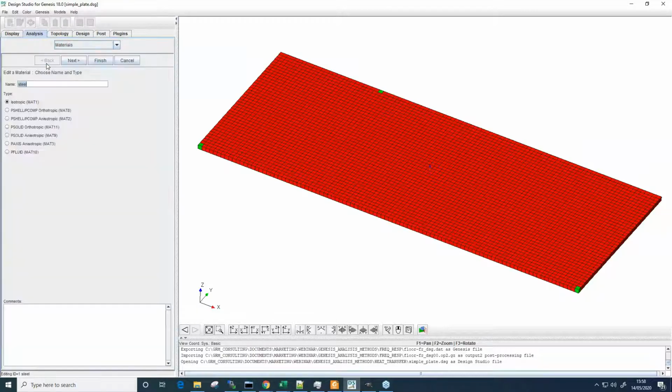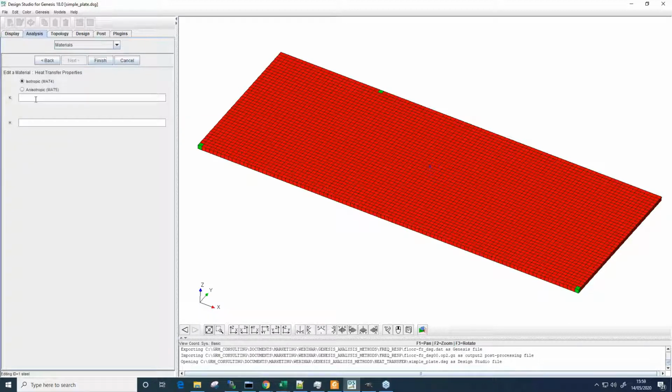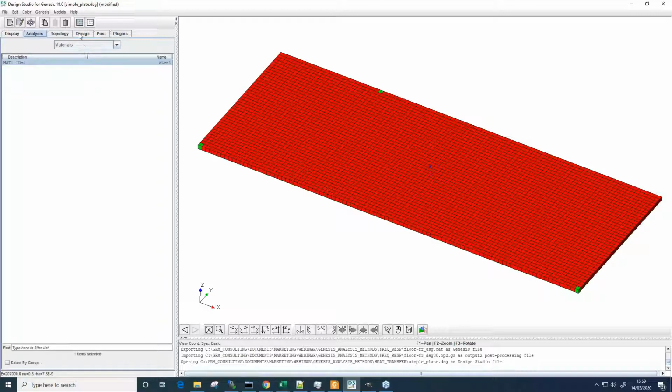So first of all, if we're doing conduction analysis, we've got our standard structural material properties here, which you'll see for steel. But what we need to define for heat transfer is conductivity. So in this case, again, through a little bit of Wikipedia searching and understanding materials, I can define thermal conductivity of steel as being 0.05, and that's watts per millimeter Kelvin. So that's the unit we're working with here. It's the amount of power per distance degree that we're traveling along. So I define that there. If you do have convection, that's what the H term is for.